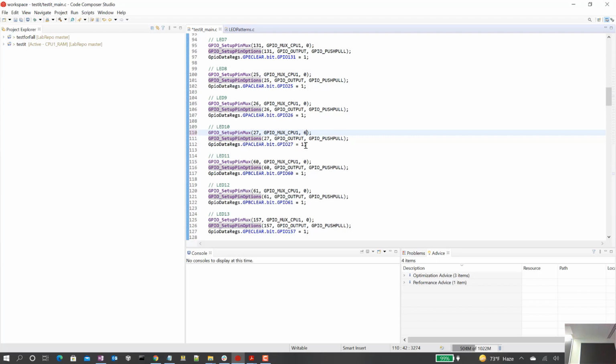The only other option you have after you set it up as a serial port pin, you do have the option to decide if you want the pull-up resistor attached or not attached. Remember we talked about this little pull-up resistor that's inside the chip on all the I/O pins? That way, when we put it to a passive push button, the signal's not floating, it's pulled up.